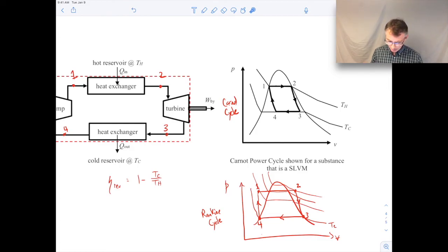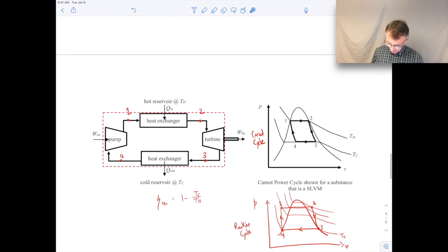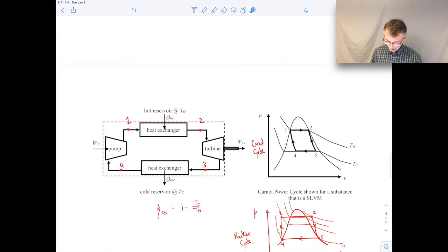The reason I'm telling you all that is we're going to come back to this point a little later in the course, so I'm just giving you an advanced preview. But the reason I'm telling you mainly is because, out of all of these different reversible cycles, the Carnot cycle is really the best reversible cycle. When you're operating between a TH and a TC, the Carnot cycle will have the best thermal performance because its average TH will be higher than the average TH for other types of cycles.